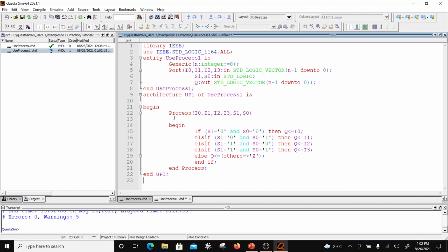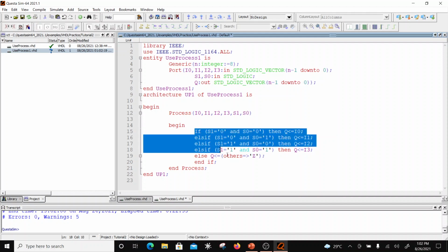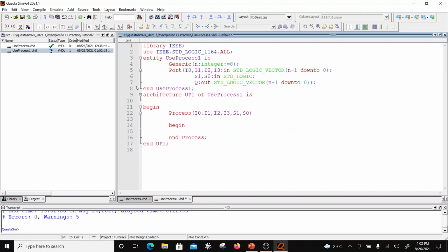So here I am going to do slight variations. This if statement I'll throw out, and I would say variable. Okay, and that is called select, and that's a std_logic_vector, a 2-bit vector, which is going to be 1 down to 0. So this is called a variable declaration, and variable declaration can take place in the declaration section of the process and declaration section of functions and procedures. So we'll come to functions and procedures later.